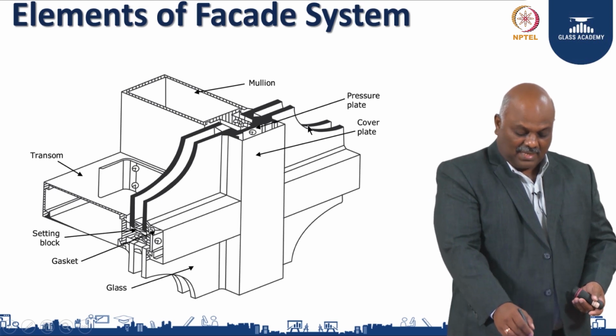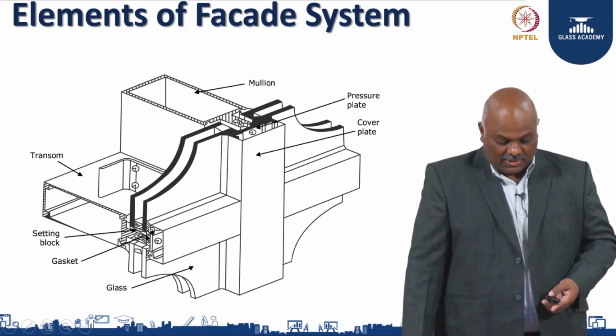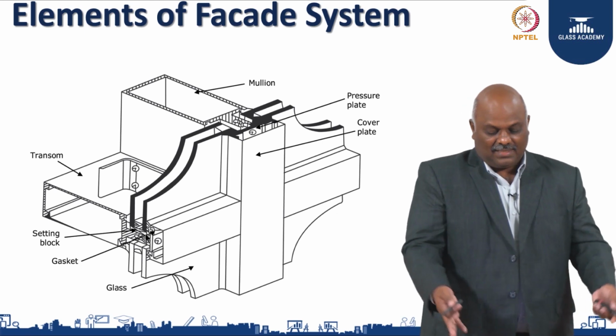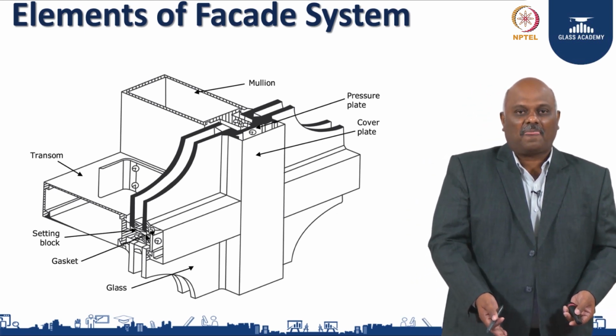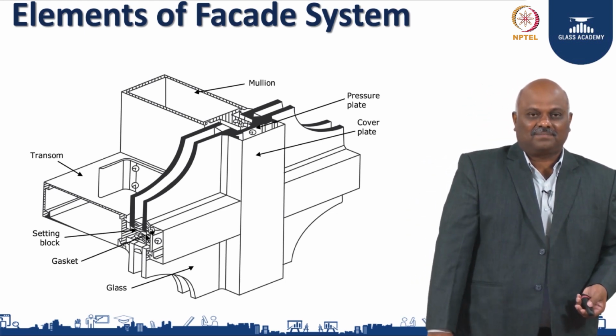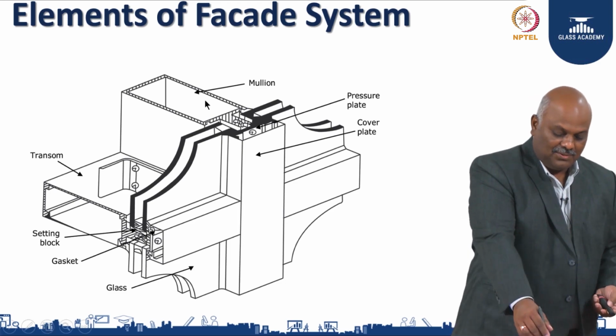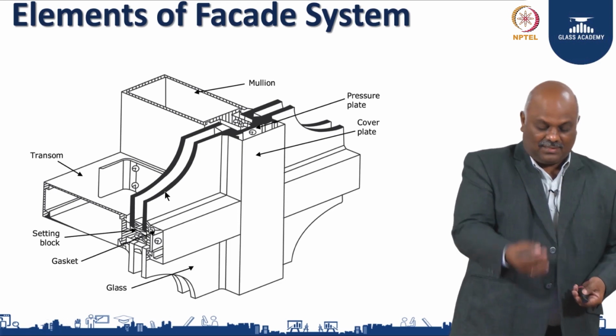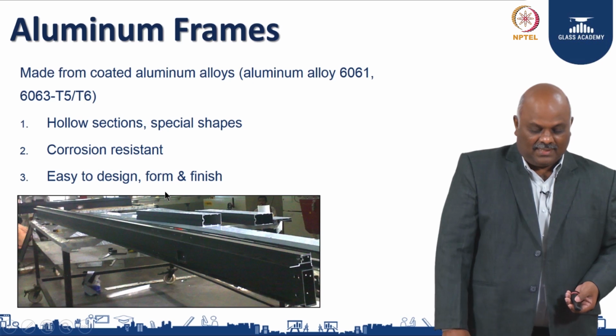This is a glass, then they have a mechanical pressure plate to hold the glass in place. This is a simple representation of a stick system. So, all this you do at site and then you get the glass and then you put them at site.